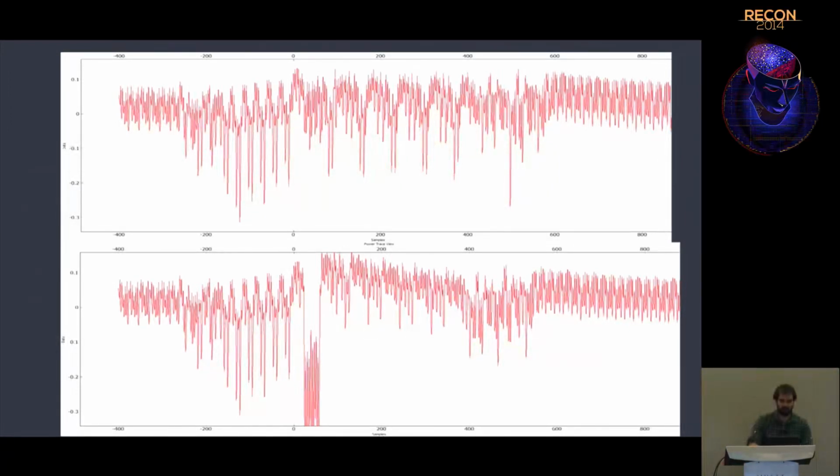So you can see, for example, that some of these loops here, this is actually the while loop going over that 5 or 6 times through the counter. So you can insert a glitch trigger on something like here, which is, I don't know, some initialization code, and then insert the glitch occurring, this large power consumption dip. So in real life, you'd use something like that, but for reliability reasons, I have it set up to do an I/O line.